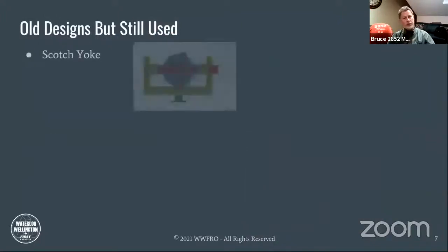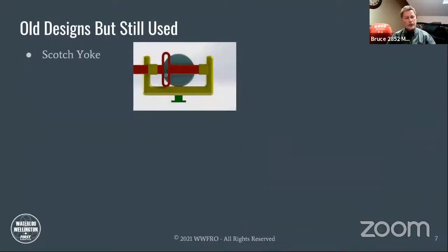So here's an old design, but still possibly used. It's called a Scotch yoke. You can see a rotary disc being driven, has a pin on it which slides in a slotted yoke, and the slide actually causes a forward and back motion. Rotary motion to a linear motion.